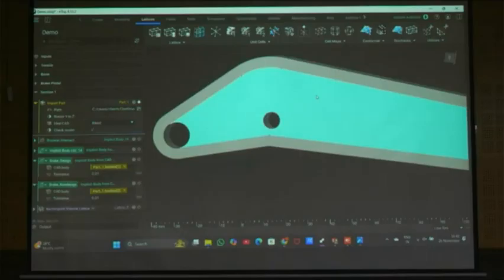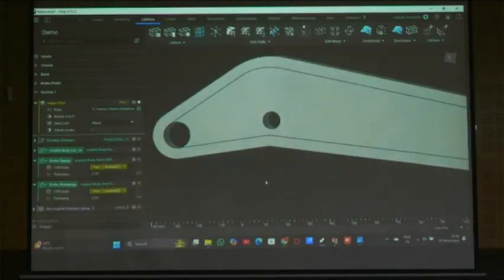Splines or other, we can separate the two bodies. That is a, I think, step file is there, okay. Actually, I designed in SolidWorks, and I separated this body in SolidWorks only. There I did actually. So you will get it there, and you can separate it. Bone means STL, right? So we cannot play STL in SolidWorks. So that's why I prefer nTop here. Okay.